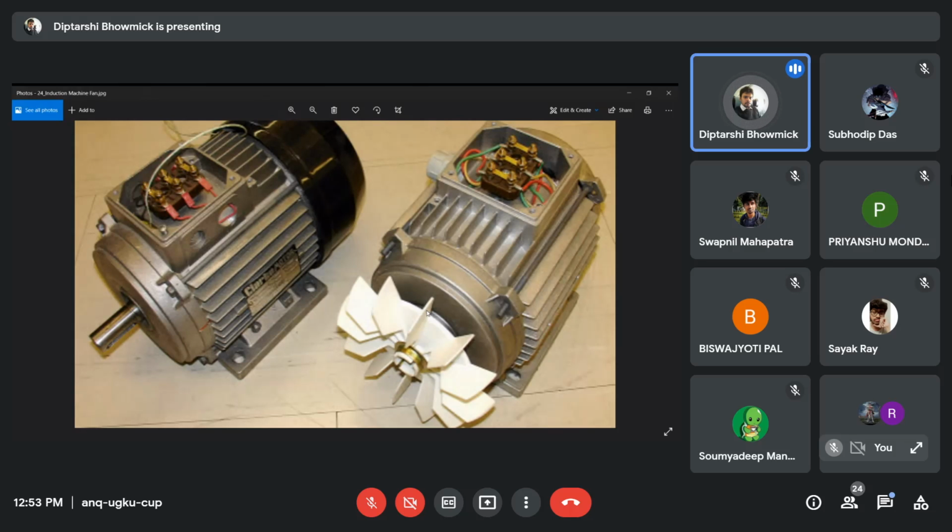But when we change the phase sequence, the wind comes out from the machine, and the machine will not be cooled. So the ventilation will be inferior when the motor rotates counterclockwise, and superior when it rotates clockwise.